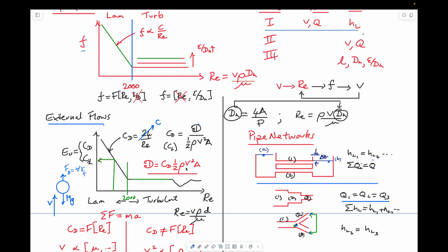Typically solve for the velocity as an unknown, where you know the cross-sectional area of your structure, you know the density of the fluid that it's falling through, you know a coefficient of drag because of the regime you're in, and therefore you can balance forces just by a free body.